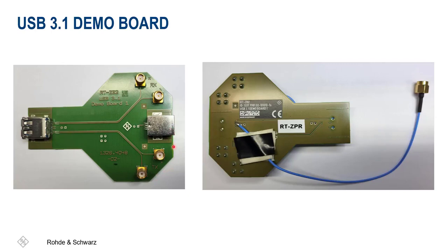Oscilloscope analog channels 3 and 4 are connected to the TX line, consisting of single-ended coaxial access points to 50 ohm transmission lines, including SMA connectors for oscilloscope connection. As soon as the memory stick is powered, it sees 50 ohm single-ended or 100 ohm differential termination, and then it automatically starts the link training bit sequence. By using this demo board, I'm able to measure the USB data signal without setting the USB memory stick to a special test mode with some external stimulus.